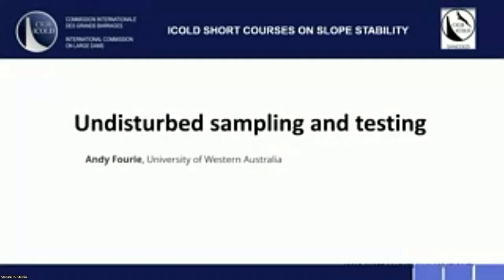All right, me again. One thing SW mentioned, I think, is really important. At the moment, to be working in tailings is really challenging, but with incredible opportunities. If I think back, like 20 years ago, people were designing a tailings dam based on 3 SPTs and 1 triaxial, and that was it. And I think that the standard in conventional geotechnical engineering, foundations, retaining walls, and all of that was up here, and tailings was down here. I don't think they've moved a hell of a lot, but I think tailings is now up here.